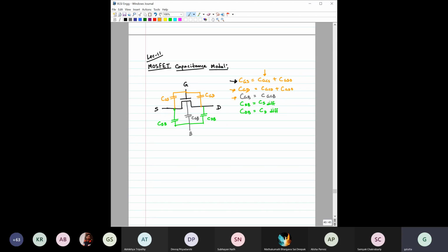Now, one of you has asked, and I just wanted to clarify: when the transistor is in cutoff, say at Vg equal to 0, how can it have a capacitance? It does not matter what the DC biasing condition is. Even if the bias applied between these two terminals is 0, the capacitance still exists. It does not depend on the DC voltage across that capacitor. Maybe we will discuss this more tomorrow, regarding how these capacitances are measured, that is, suppose you have to measure any capacitor, how do you do that?